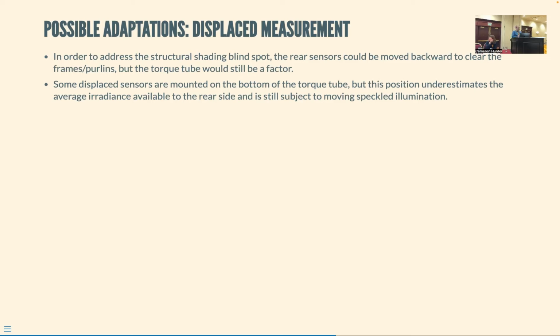If you're trying to cram this capacity test into 2 or 3 days, it's not really very helpful, which is even exacerbated by the previous presenter saying, look at these half hour I've got at the beginning and the end of the day that makes sense. You could have a quite radically different rear side irradiance or very similar rear side irradiance and not see any variation that you're depending on for your regression in the test.